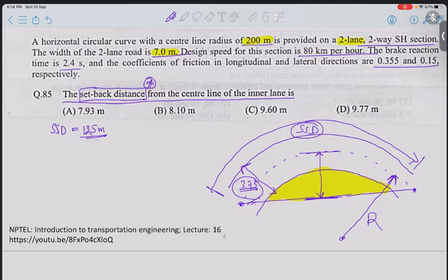So let me tell the answer then. Can I speak? Yeah, sure. Yeah, actually, before providing this distance, we need to have a certain required side distance. In order to make the available side distance more than the required side distance, we are providing the setback, in order to avoid that obstruction which makes the side distance less. Very good. Correct answer.